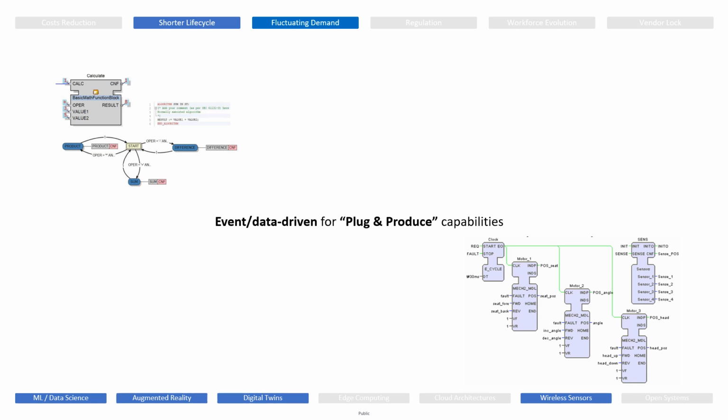This makes distributing controllers across the entire network possible, with control logic running directly on sensors, transmitters, controllers, and even in the cloud. This results in a more scalable and distributed control system instead of centralizing all control tasks. Different parts of the control logic can run where it makes the most sense, at the edge, directly on a field device, or in the cloud. This allows control functions to be executed closer to the data source, reducing latency and making real-time control more effective.